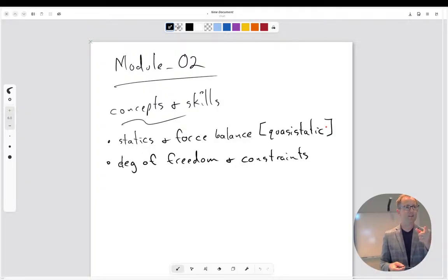Yeah, so if you have all these moving parts and you start hooking them all together, then you reduce total system degrees of freedom. Each part might have 6 degrees of freedom, but then when you pin it into place and now it's a door swinging on a hinge, it only has 1 degree of freedom. It can only rotate around that one hinge. So every time we add a constraint, we remove degrees of freedom.